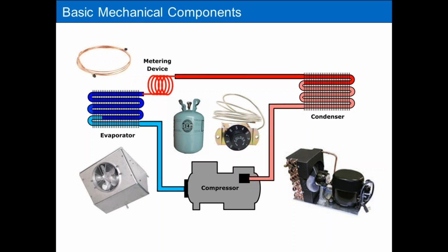You have your basic compressor condensing unit. Typically, it's going to be a reciprocating compressor, fractional horsepower. You're going to have usually a single circuited evaporator, sometimes multi-circuited evaporators, but for the most part, single circuited evaporators. We're going to focus on those systems with your cap tube metering devices, so that's a pretty simple type of metering device, but it has its complexity for sure.